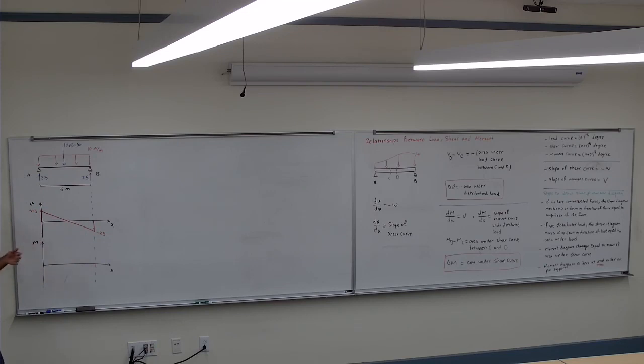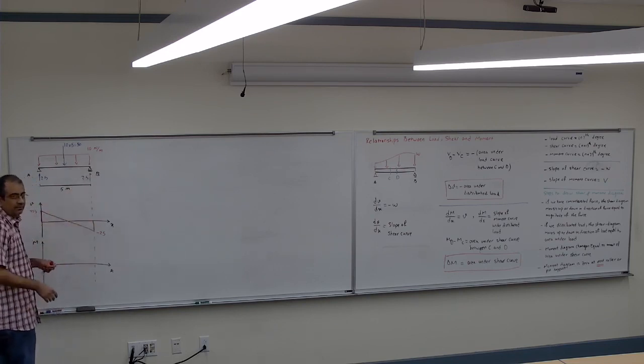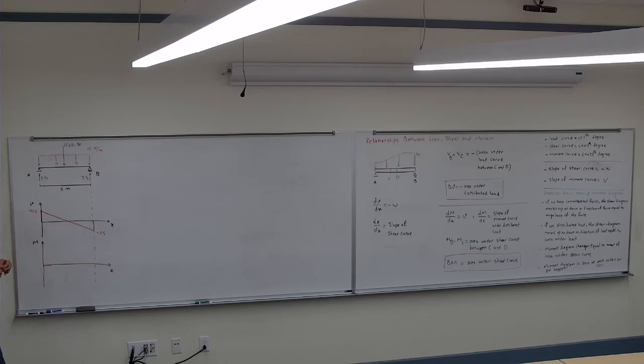So that's your shear. Right now, you have that red line at the end going back to 0. Is it meant to go back to 0, or is that just to show that, because if you cut it right there, it's 0? Oh, okay, gotcha. So you got it? You don't need to cut anything, you don't need to write any equation, you don't need to write any equilibrium, as long as you know those rules.